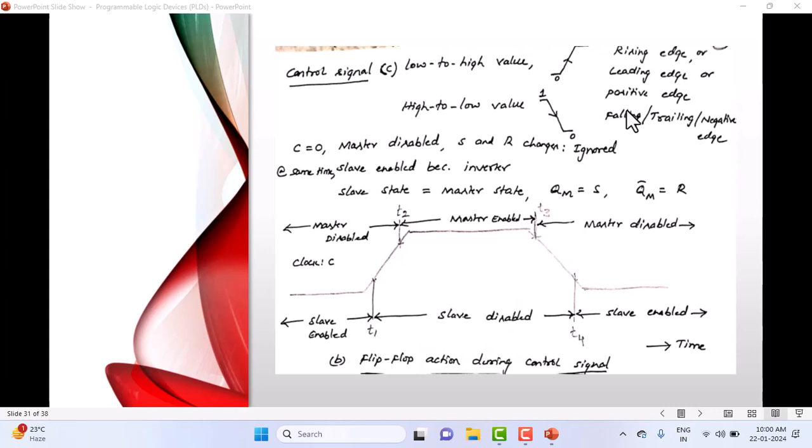See, it will take its own time. And fall time is the reverse, just the opposite of the rise time. The time taken by the clock to come from high level to the low level. Okay. These are the parameters. When you design this in a tool, you are supposed to give all these parameters as an input when you design a clock. Blindly, we can't design a clock with sudden rise and sudden fall because practical circuits will not generate a clock with sudden rising and sudden falling.